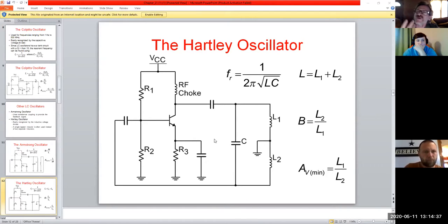And the way that you set that up is you're doing it as a sweep. Now, what the hell does that mean? Now, I'm sure you found out if you actually had it running. Now, do you do a continuous sweep or do you do a single sweep? Are you feeding it a pulse? Are you feeding it a sine wave? And that type of thing. And LT Spice is very tricky when it comes to that type of thing. So you have to define your input.